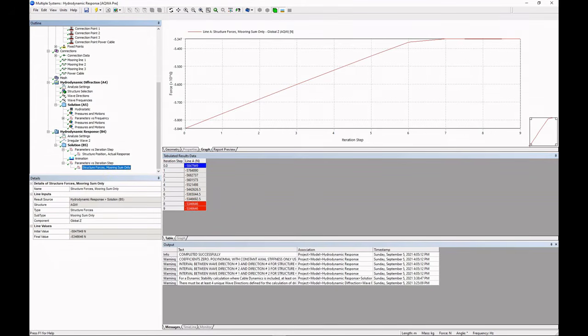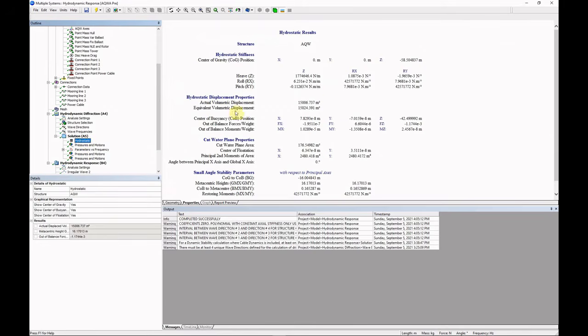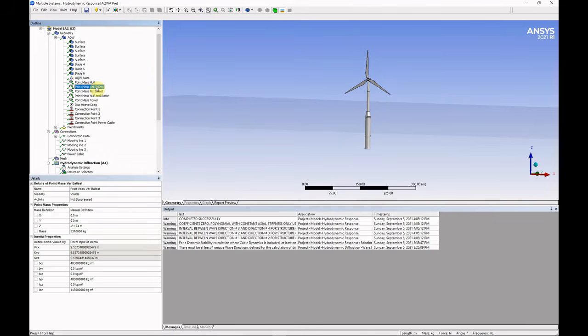Ansys total vertical force is lower than that estimated in the spreadsheet. The main reason is the power cable top tension was wrongly calculated as taut leg, and the total free hanging length is also wrong. If we use hydrostatic stiffness of the hull and the distance it has sunk, we can compensate for this force difference in draft by removing variable ballast mass.